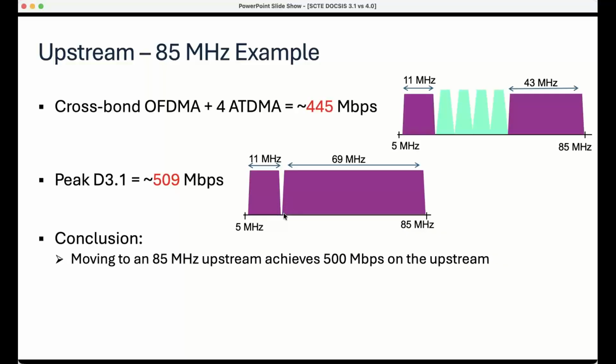And the reason is this will allow your modems to still use this smaller OFDMA block in the noisy spectrum, but at a lower order modulation. The larger OFDMA block will ideally be usable by the cable modems, but at a higher order modulation, because somewhere above 20 megahertz or so, you always see the noise drop significantly in the return path. So this can operate at a much higher order modulation. You get much higher data throughput, and that's ideally what happens.